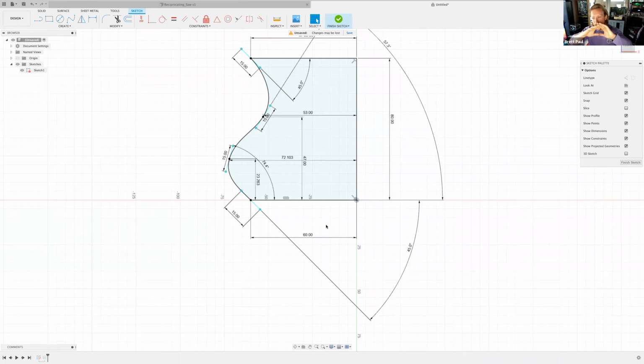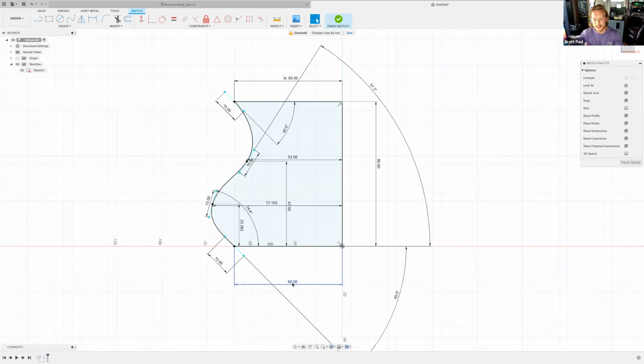So this is all to say, the whole intention here was to make this skinnier, and we wanted the outside profile to stay the same. I think it's even worth pointing out, if I had not made this dimension a function of this here, if I said this dimension equals 60 or equals D2, then this would shift and that point would stay the same.